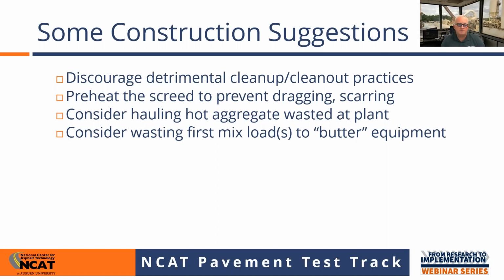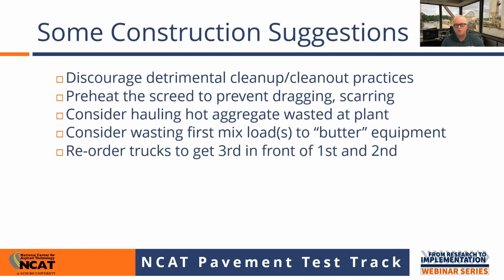And if you do have some cleanup residue on the equipment from the previous day's run or the previous night's run, then that mix that you run through can kind of clean that up a little bit before you start putting paving mix in it.